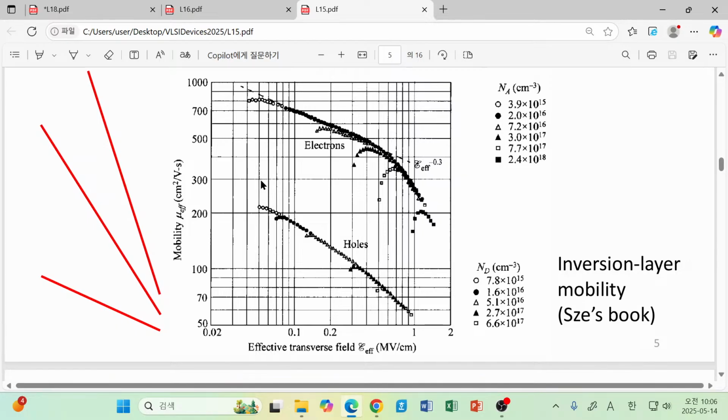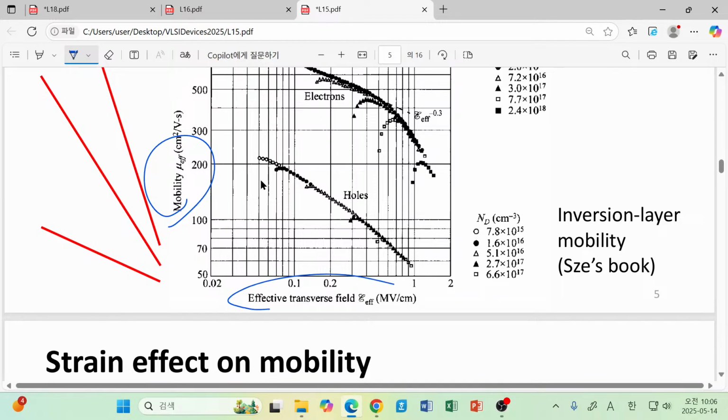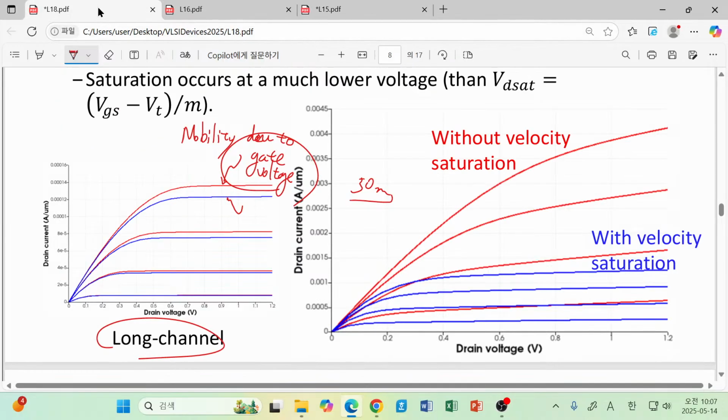This is the effective mobility of a silicon channel, and maybe you remember that this effective mobility has some factors like oxide field and silicon field, and there are certain numbers corresponding to a half or 1/3 depending on polarity. NMOSFET and PMOSFET have different numbers. But anyway, this effect was considered in this red curve.